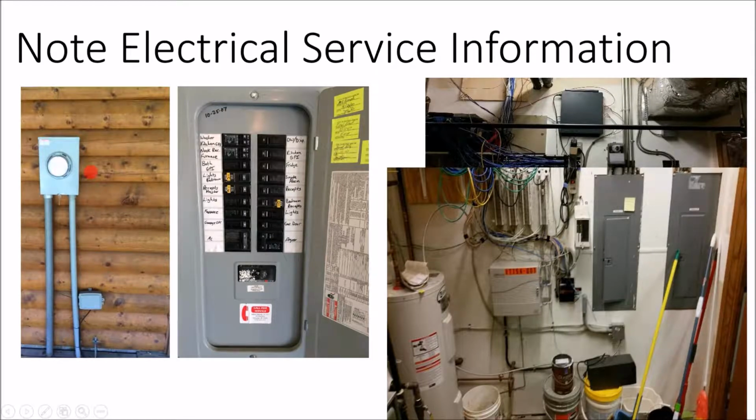This picture here on the left is pretty revealing. What's revealing to me is that we have two conduit sizes. So this is a log cabin, and on the other side of this wall is the service panel. And what we have is an underground utility feed coming up into the meter, and these oversized cables, and then coming out of the meter in this smaller cable. That's what's going into the residential home, because they wouldn't have larger conductors going into the residential home than this underground service feed.